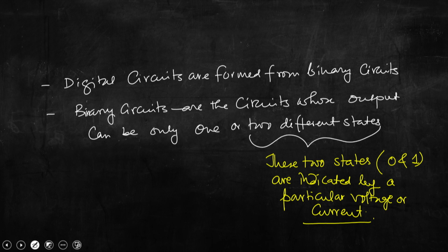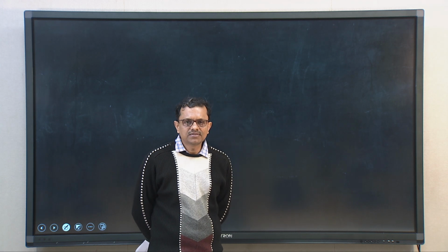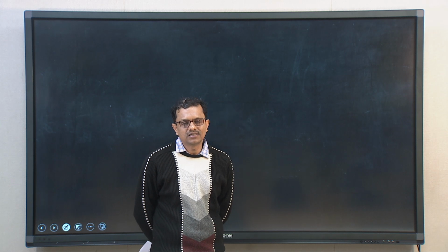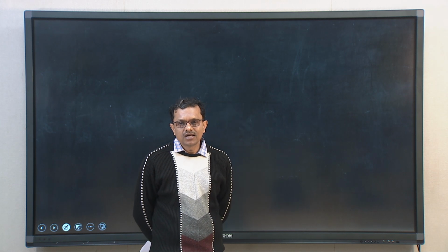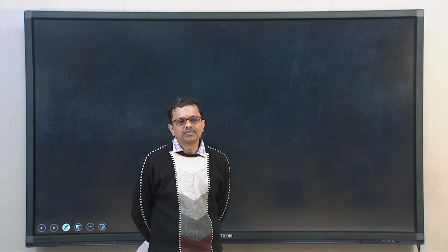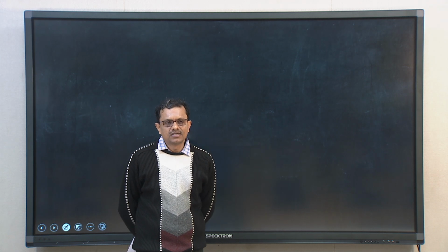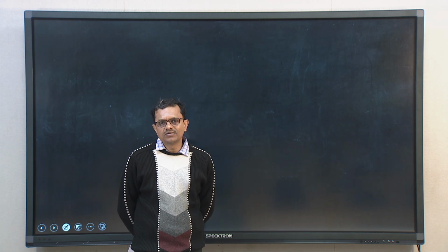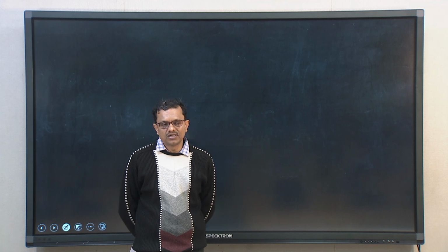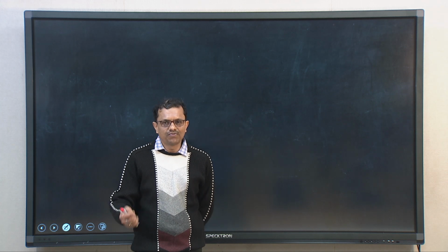You know that in a digital electronic circuit, transistors are used as a switch. We studied in our previous class that transistors can be operated in 3 different regimes: cut off, active or linear, and the last one is saturation. If transistors are operated in both the cut off and saturation regimes, then they can be used as an electronic solid state switch, that is on and off.